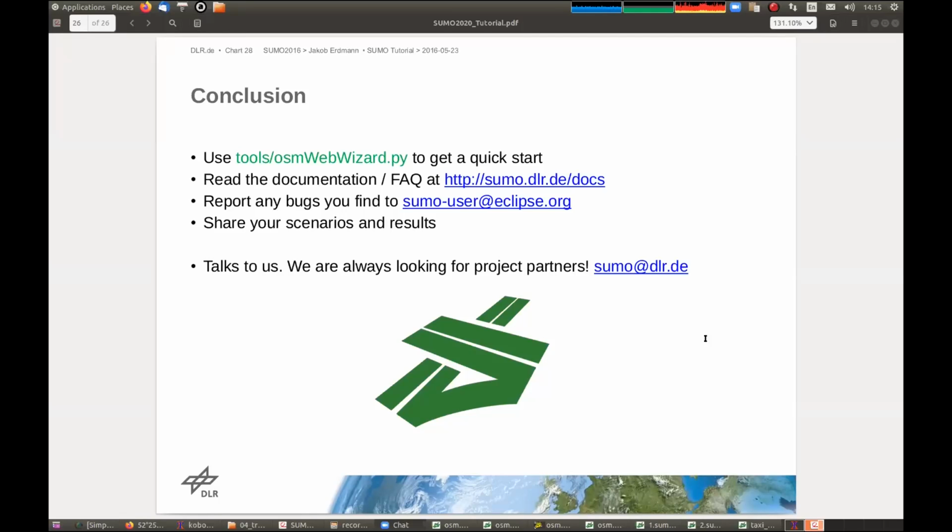So it's very hard to model that autonomous vehicle, but you have various configuration parameters where you can explore the different assumptions about how the autonomous vehicles will differ from the human drivers. But you will not find this in the mesoscopic simulation because it's too coarse for that. There you can specify the expected flow rates, but the differences between human and autonomous drivers will probably be on a smaller scale, on a more microscopic scale.